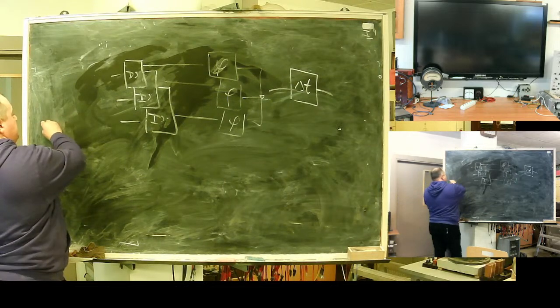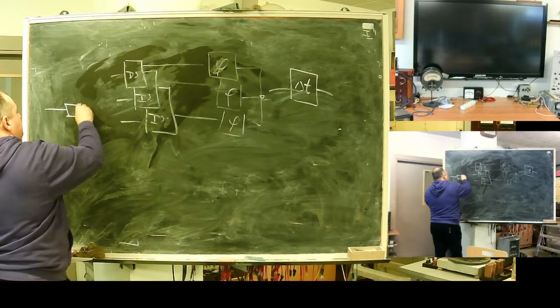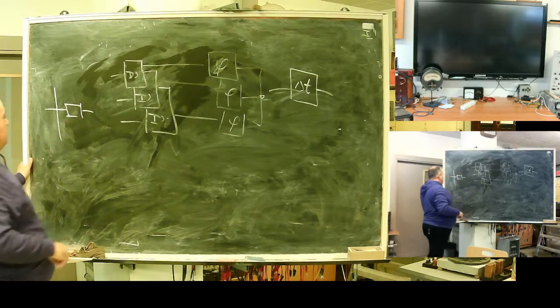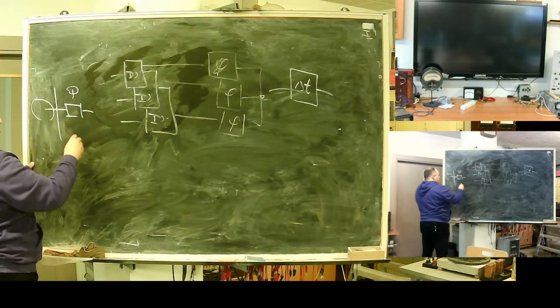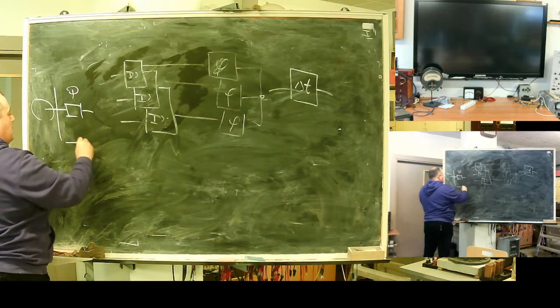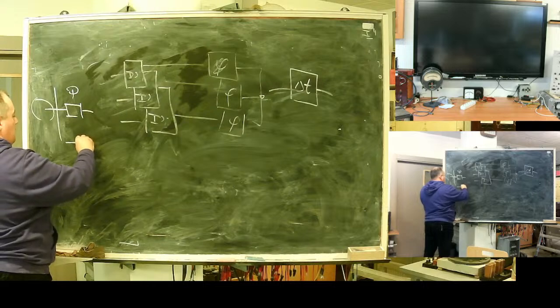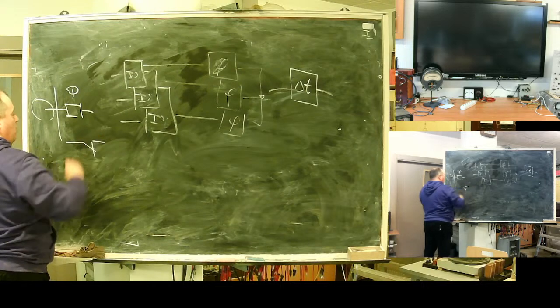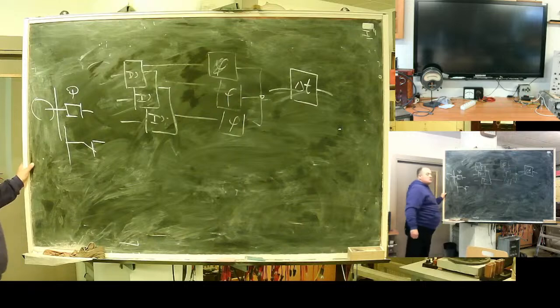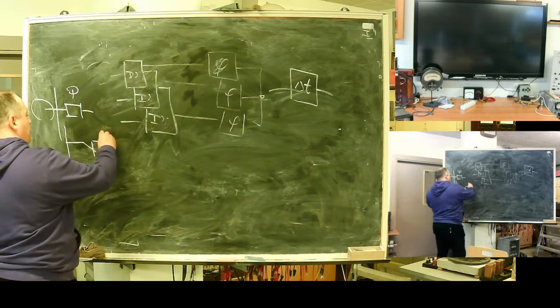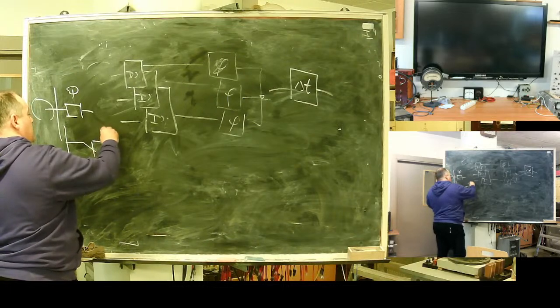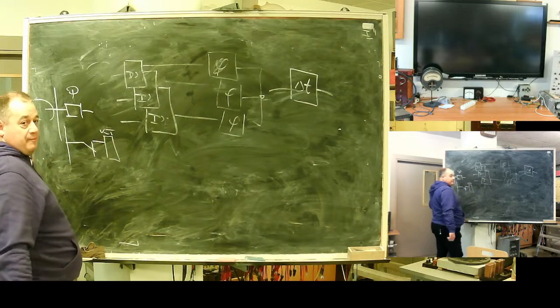What's the idea of speed? You have your power switch, or your circuit breaker. Take normal closed contacts of the circuit breaker and apply to timing relay.